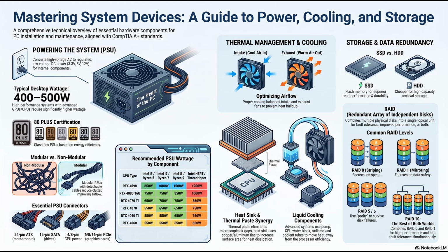Most people just cram them into a giant knot at the bottom, which looks terrible through a glass side panel, but more importantly, it creates a physical wall. A giant knot of cables blocks the intake fans from pushing cool room air toward the graphics card and processor. You are strangling the system's ability to breathe.